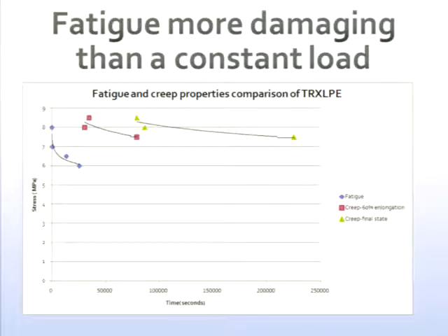If I was to, for example, apply 7 megapascals, this thing would fail in a few tens or a few hundreds of seconds, whereas if it was simply creep failure, it would last up to something like the order of 130,000 seconds. And if you worry that I'm extrapolating there, you can do a similar calculation at 8 megapascals. So this is a real phenomenon. This material is failing under fatigue under the conditions of our mechanical testing.